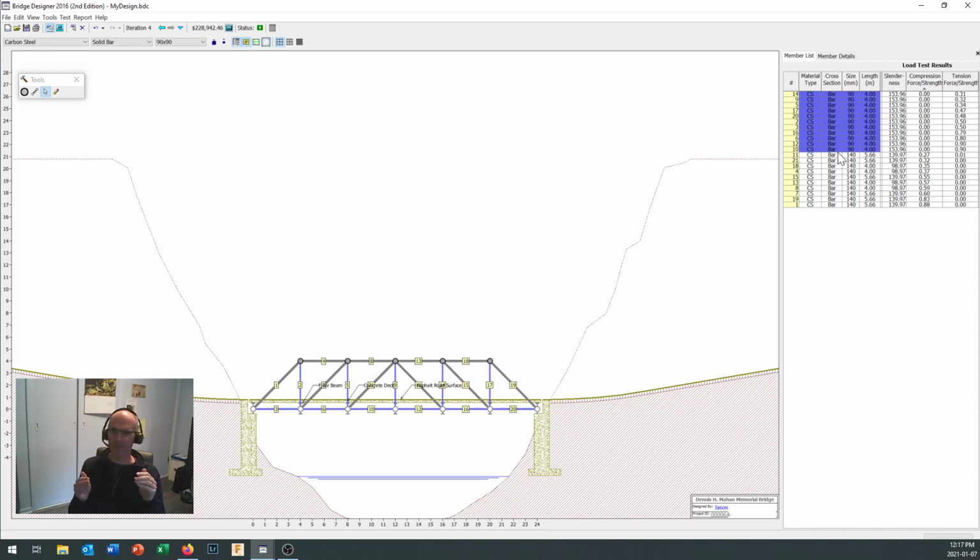The other benefit that's happened by shrinking those members down is that they've become lighter now. Keeping in mind that a large part of what the bridge needs to support is the dead load of the bridge. By using less steel, the bridge weighs less, so the bridge can be less strong because it doesn't have to hold as much of itself up. That kind of makes sense, right? A lighter bridge doesn't need to be as strong because it's that light. The weight of the truck going across there is not insignificant, but relative to the dead load of the bridge, it's not that big.